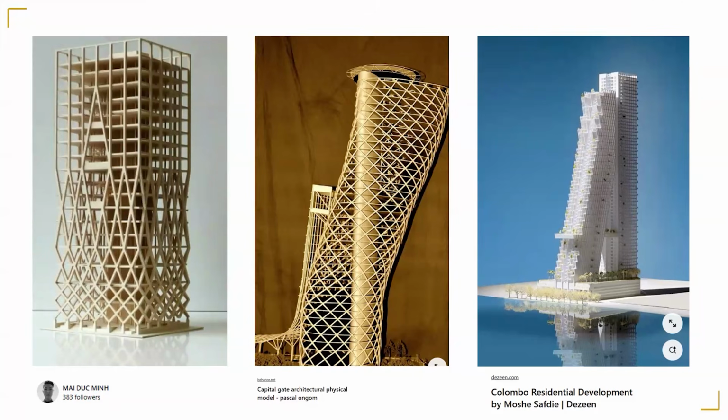So you keep generating the models every time by removing things which are not participating, until ultimately you're left with the bare minimum, most optimized form. And this is an example of that. Lower, you have a lot of diagrids. As you go up, you don't need the diagrids because now the structure is laterally not a short building now. So up on the top is a building with few diagonals, going down more diagonals, until you have this thing. It's beautifully designed.